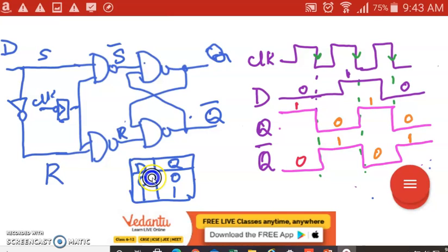The truth table that I have written here is for the latch. When I write it for the clock, just add an additional column with the application of the negative edge. You write down the down arrow. When the clock has a negative edge, D 0 gives Q 0, D 1 gives Q 1. What if there is no clock?